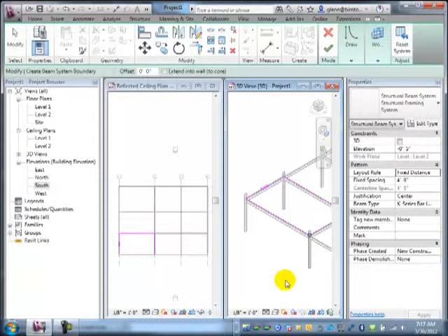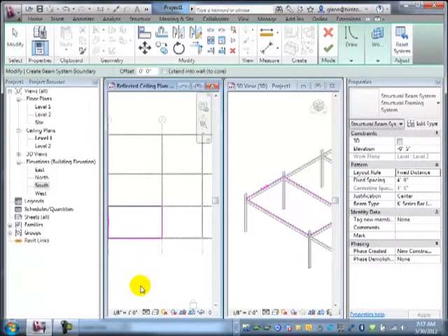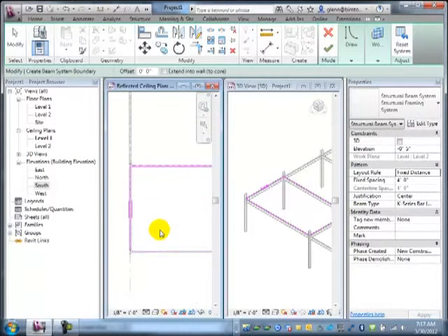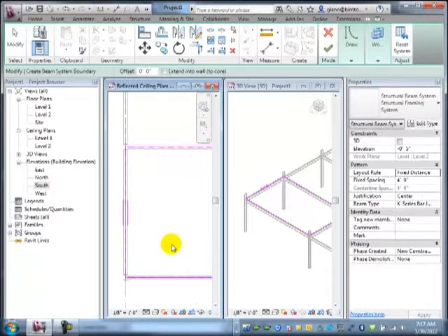You might see right in there, there's a little circle that shows up when I do this in plan, after I select beam system and select the distance. You select whether you want it centered, or at the beginning or at the end. There's a circle that shows up, and I just touch the beams that are on the side, and it installs it. I'm trying to think, are you working in Revit Structure? Yeah. Okay, because it's a little different between the two.